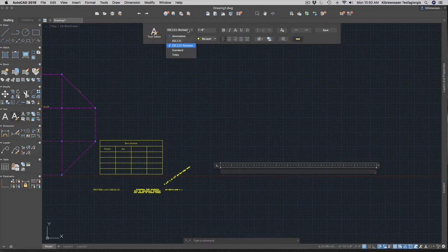You see what makes this one really fantastic, the multi-line text. It gives you an option to make edits where you are writing. So I'm going to choose titles here. Now you see, it shows me what height I'm going to use, and if I'm using a particular layer, it will allow me to use a particular layer.